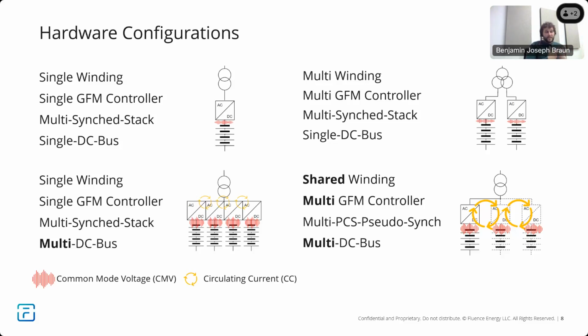But in terms of grid forming controls, it's pretty convenient because you've got one voltage controller behind its impedance from its own transformer. It's galvanically isolated from any of the others. The risk of circulating current is non-existent. You could still have some oscillations with other systems, but because of that impedance, you're pretty safe.